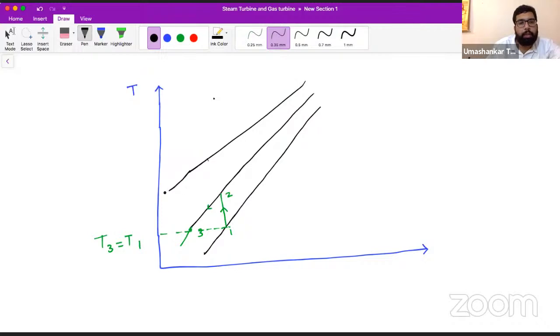Firstly, I'm making the ideal cycle. From 3 to 4, again second stage compression is taking place. And now we are going to this T5 point, where heat addition takes place in the combustion chamber, and then we will expand to point 6, and 6 is above 4, as you can see.